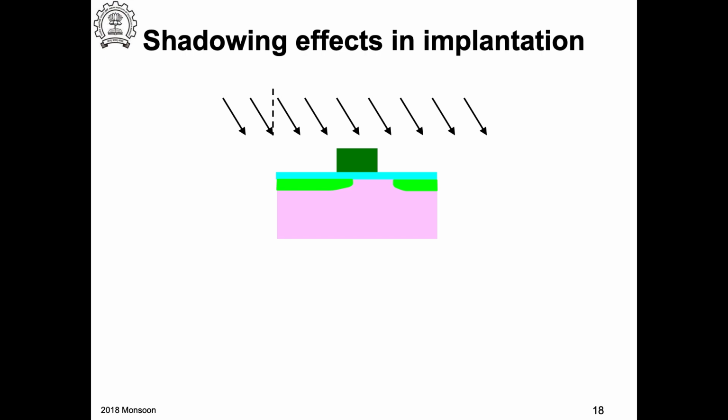So basically electrons are here and you are lowering the barrier for electrons to flow into the other region. This is like you are forward biasing the PN junction, essentially. But in this case you are doing it by coupling the voltage to the PN junction through a capacitor. That is a gate capacitor. So this is what you are doing.